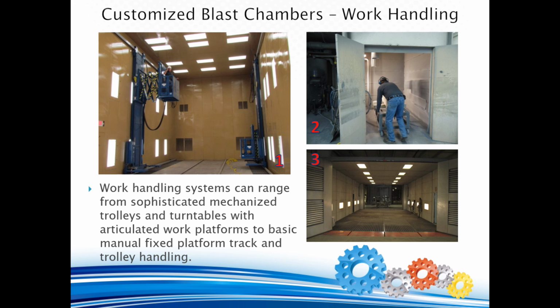Finally, image number 3 shows an alternate blast room layout to suit inline production operations by having 2 sets of doors, one on each end of the blast chamber. If multiple trolleys are used, abrasive blasting downtime can be minimized because the extra trolley containing the unblasted workpiece can immediately be moved into the blast chamber for immediate blasting after the blasted workpiece on the other trolley is moved out from the opposite end of the blast chamber.